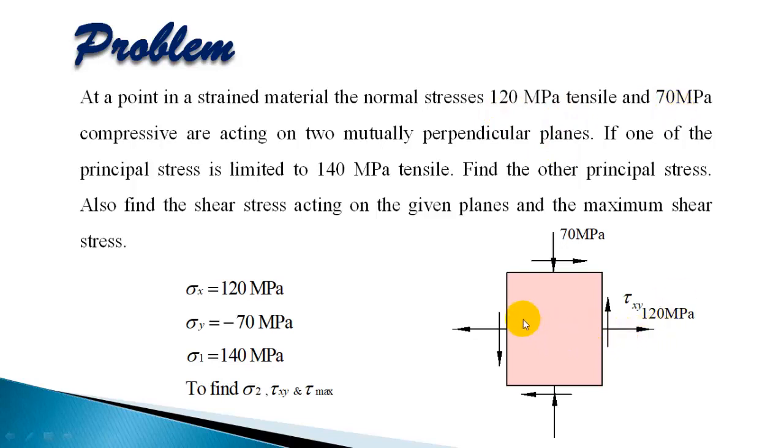So that's not going to make any difference in this solution, but the stress on a given plane will change. So if you are taking this in the x direction on this particular plane, the stress values depend on this direction, but principal stresses and principal planes are not going to be affected by these directions. So you are given one of the principal stresses, it's limited to 140 megapascal.